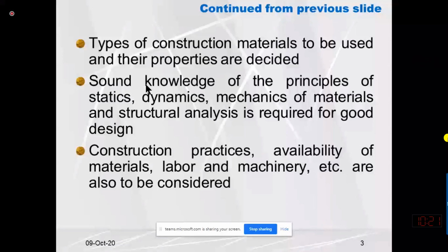So then the second option is that I will use a bolted design, and again I will check what diameters of bolt are available in the market. If in the market 15 mm diameter and 25 mm diameter bolts are available, I will not design the bolt connection using 20 mm diameter, because that bolt size is not available.